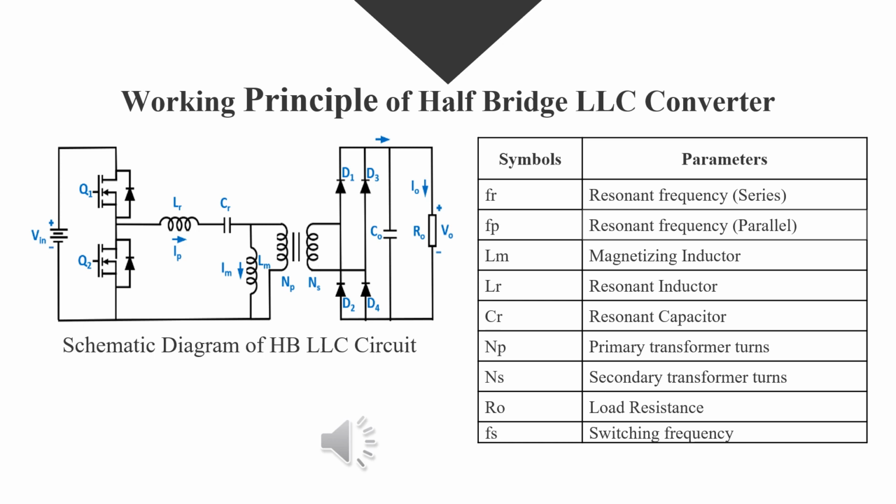Fundamentally, the resonant network of a series resonant converter presents a minimum impedance to the sinusoidal current at the resonant frequency, regardless of the frequency of the square wave voltage applied at the input. This is sometimes called the resonant circuit's selective property. Away from resonance, the circuit presents higher impedance levels.